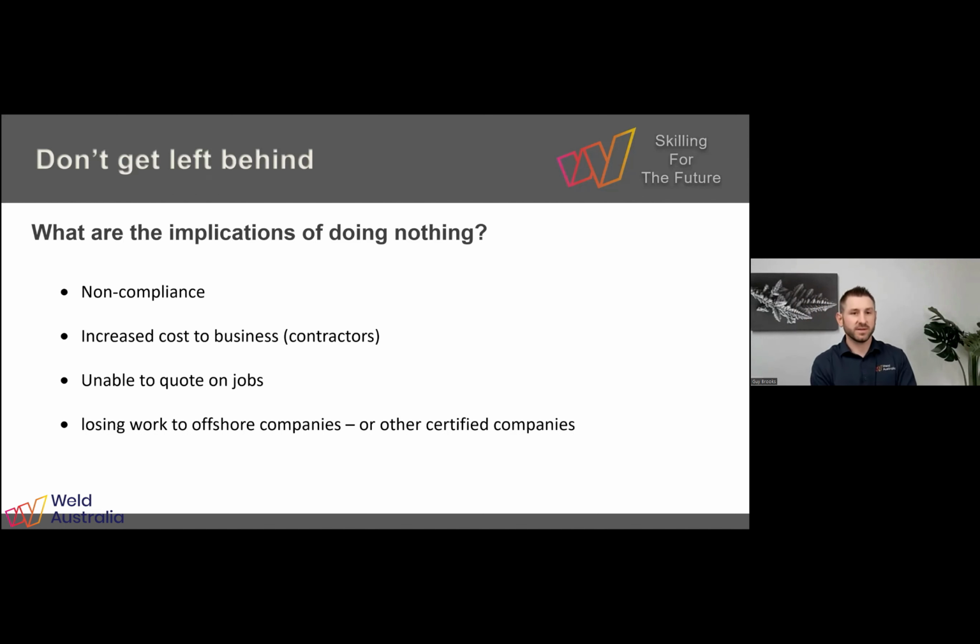So an increased cost of business, through contractors and those kinds of likes, right? Unable to quote on jobs. I'll show you in a minute some of the standards that actually specify 3834, welding supervisors, inspectors, things like that. Then, losing work to offshore companies as well, or other certified companies. Other companies that are 3834 certified can tender on jobs that you can't, or other companies that have just welding supervisors, a Cert 10, and an inspector.